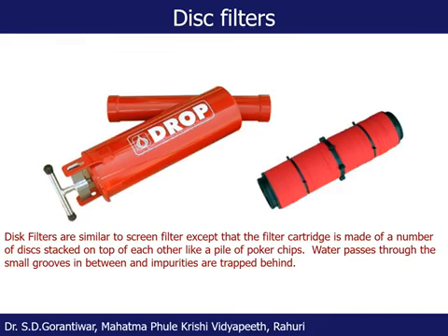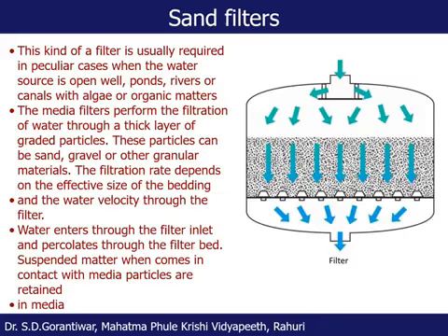So when they are stacked against each other tightly, a small path is developed through which only water can pass, and the impurities are retained over the disc. So this is the main working principle of the disc filter. And if you want to clean the disc filter, you can just remove the screen, dismantle it, and wash in a bucket. It is quite easy.